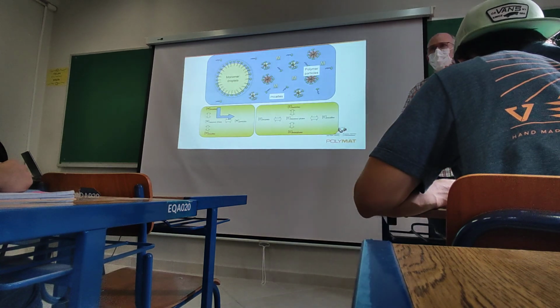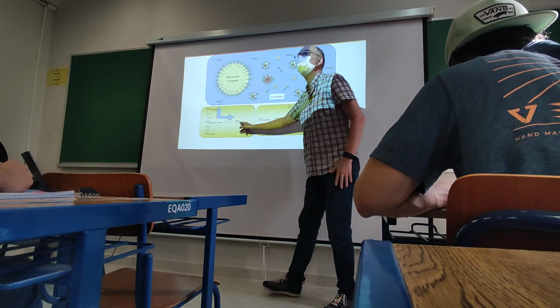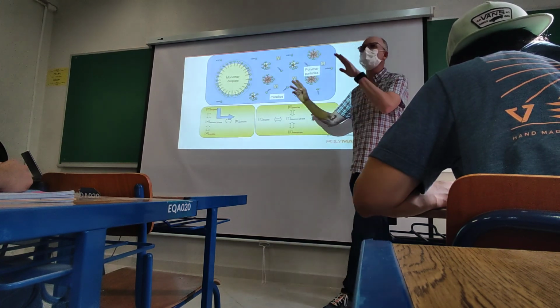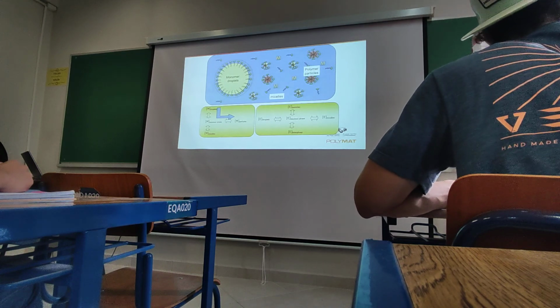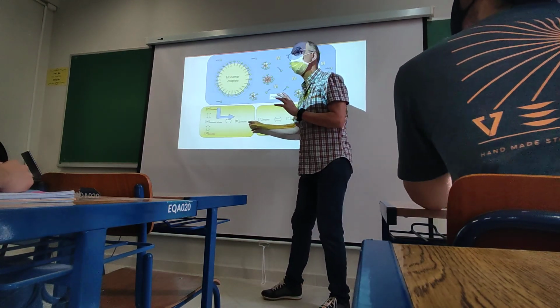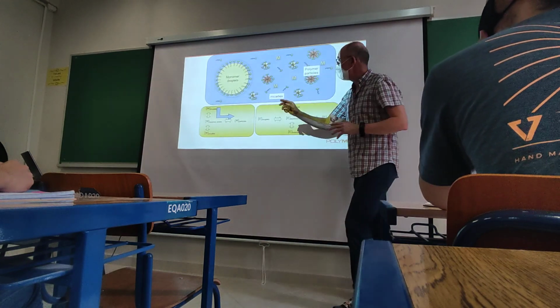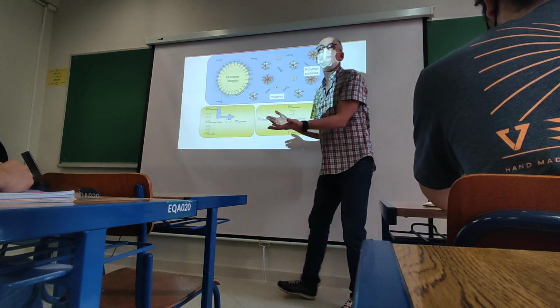If you have a monomer which is very hydrophobic, it cannot be transported through the aqueous phase, so you cannot polymerize very hydrophobic monomers in emulsion polymerization. So this is a limitation of emulsion polymerization for very hydrophobic monomers, because mass transfer of the monomer through the aqueous phase is not possible.